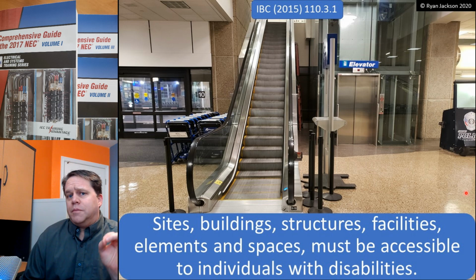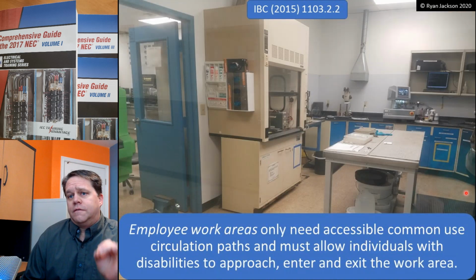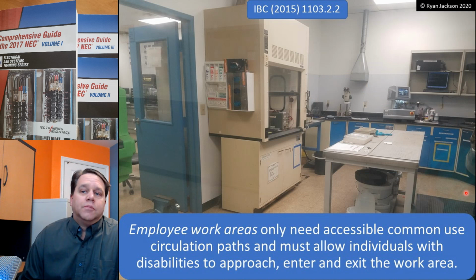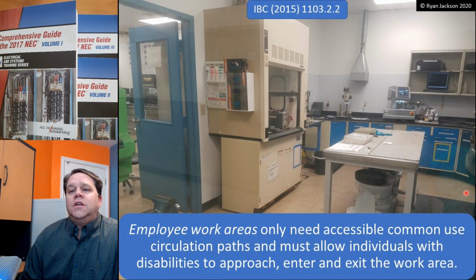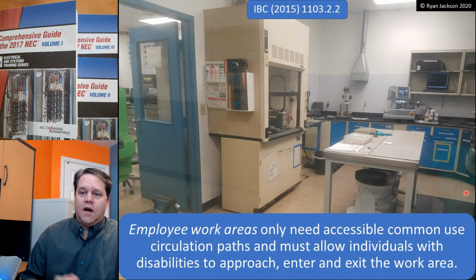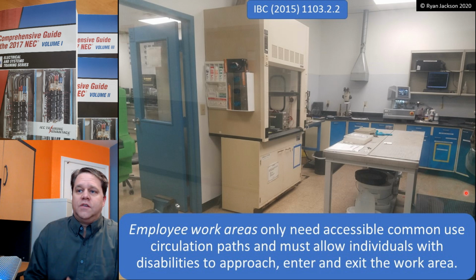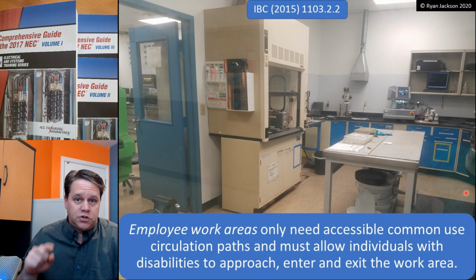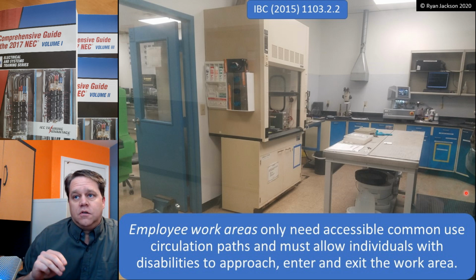So there are some blanket exceptions in the IBC. And the first one, and probably the most common, is employee work areas. Employee work areas only need accessible common use circulation paths where I have multiple people traveling down the same path. And they must allow individuals with disabilities to approach, enter, and exit the work area.